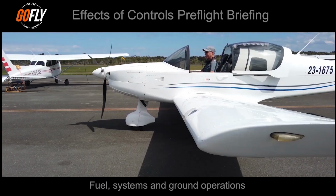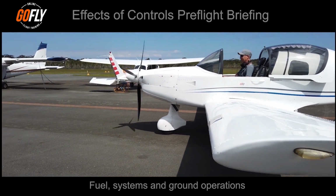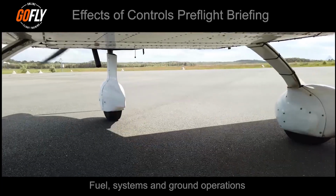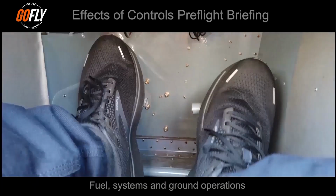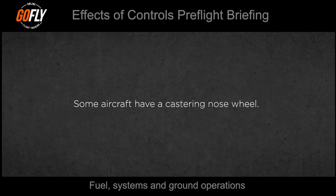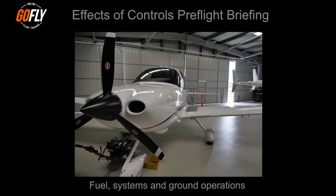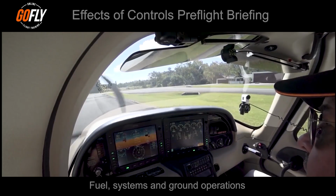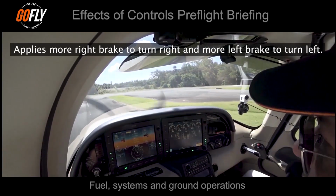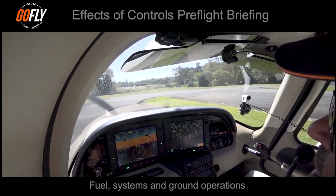pressure. Most training aircraft have a steerable nose wheel that is connected to the rudder and steered with the rudder pedals. To move to the right, the pilot applies pressure to the right rudder pedal, and to move to the left, the pilot applies pressure to the left rudder pedal. Some aircraft have a castoring nose wheel. This means the nose wheel moves freely. With a castoring nose wheel aircraft, the pilot has to use differential braking to turn the aircraft. To turn the aircraft, the pilot applies more right brake to turn right and more left brake to turn left. The pilot applies pressure evenly to both brakes to slow down or stop.